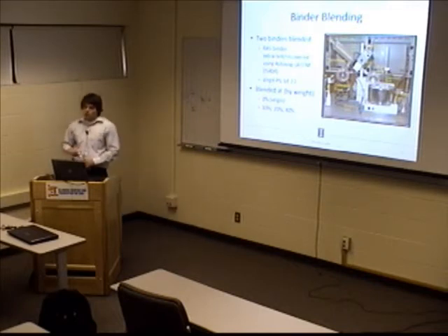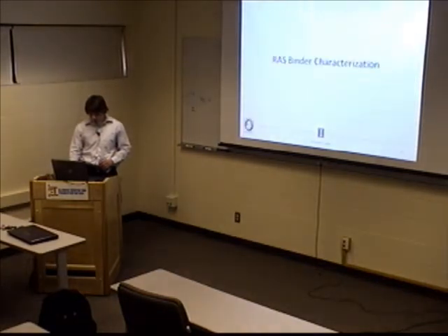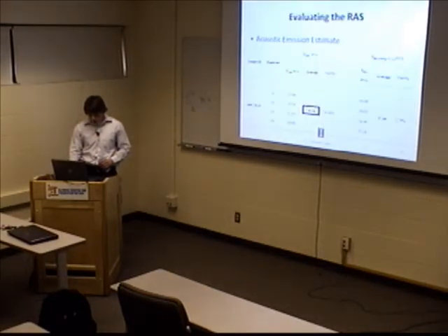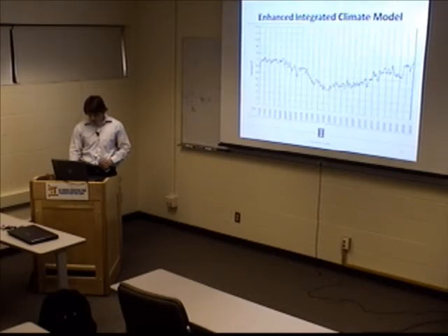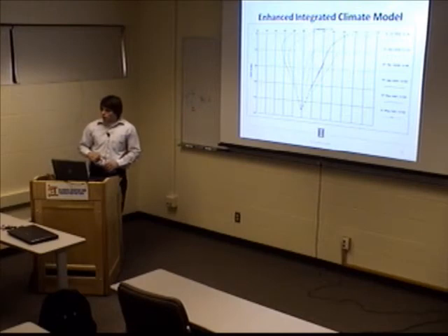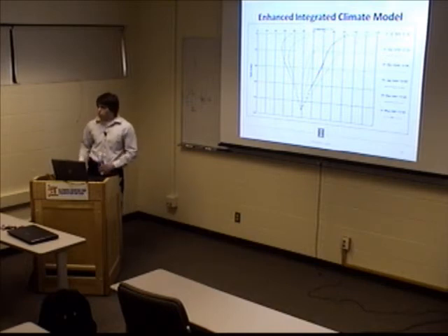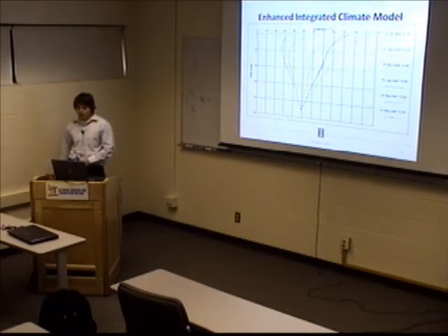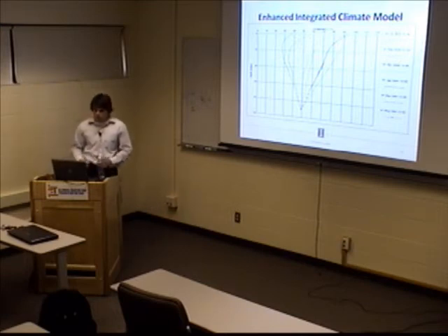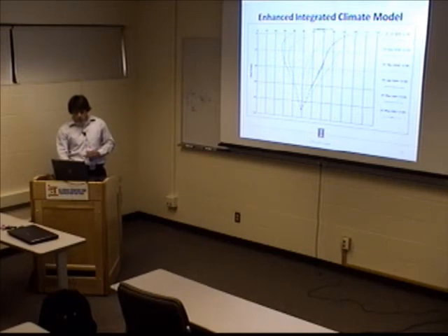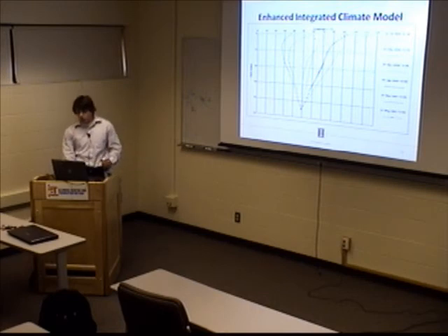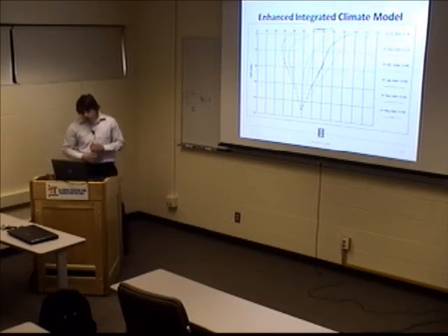I think if we did run a climate analysis, I can go back to that slide. Isn't that exactly how that's come up with, though? Isn't it based on temperature lines? It might be. For example, the BBR is correlated to a certain cracking potential. It's almost like an empirical value. But you could run an MEPDG type simulation here, using this temperature fluctuation, and get something like that.